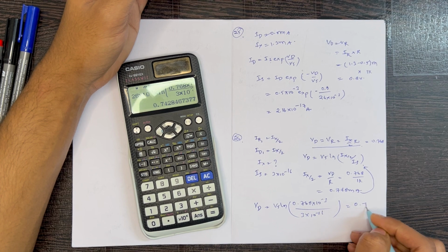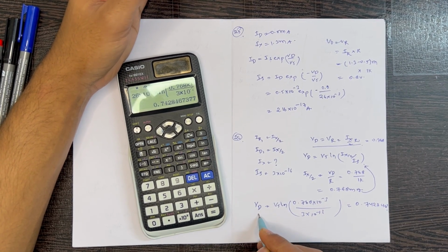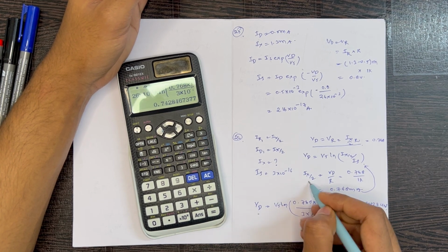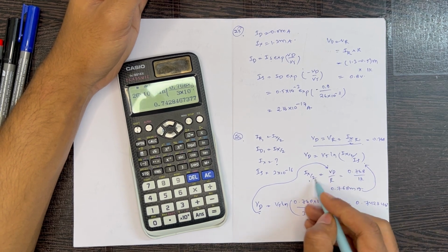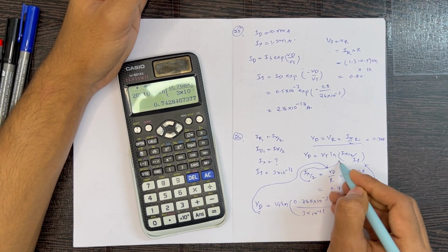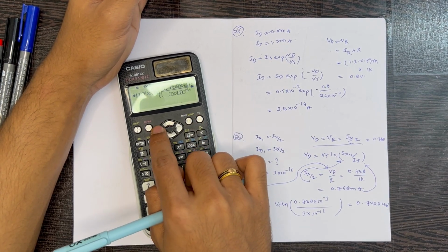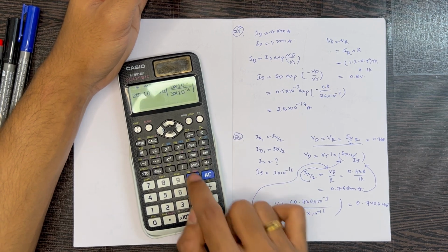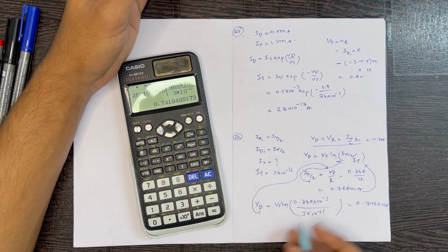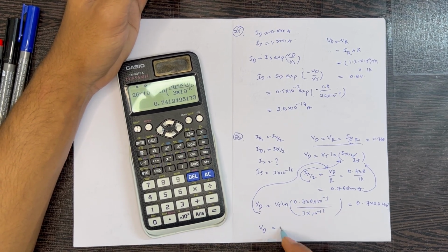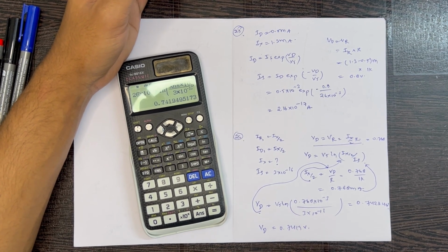This is 0.74284 volt. So using this as a new Vd value, we'll calculate Ix by 2 again and solve this iteratively. We'll get the Ix by 2 new value and we'll put this value here. So using this as an answer, we'll just iteratively calculate here. As you calculate that multiple times, you will finally reach a saturated value, that is 0.7419 volt. Okay, we need to calculate Ix.